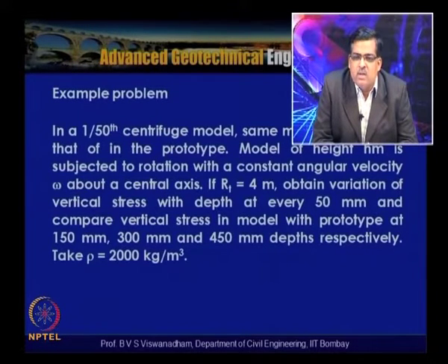prototype are identical, that is where the d sigma will be 0. At a depth of around 150 mm, you will see that the under stress error is maximum. And at depth Hm, that is at the base of the model, Hm equal to 450 mm, you will see that the vertical stress in the model is more than the prototype stress.